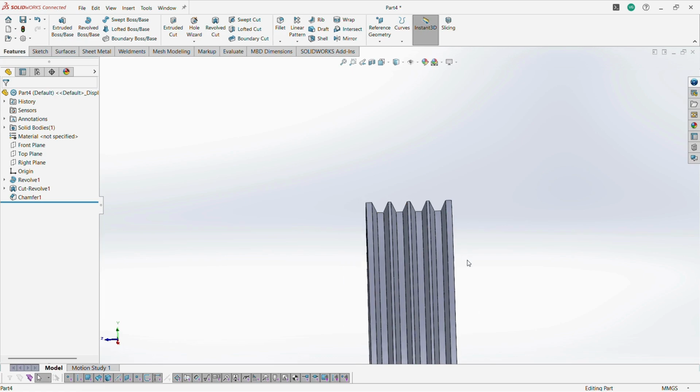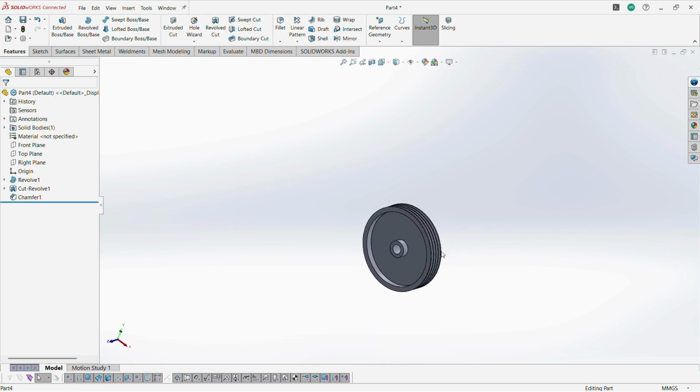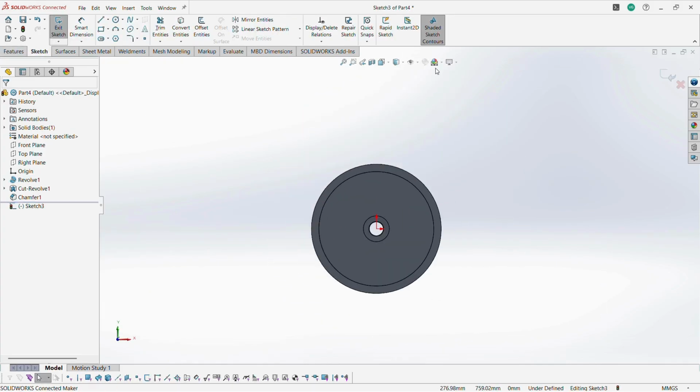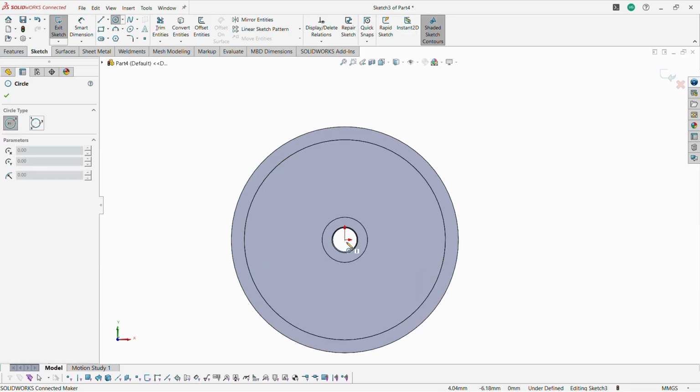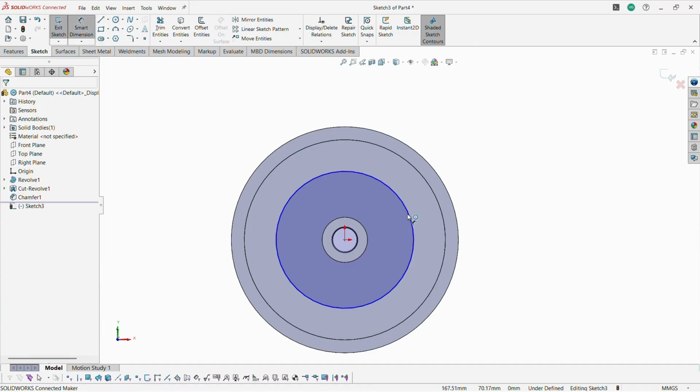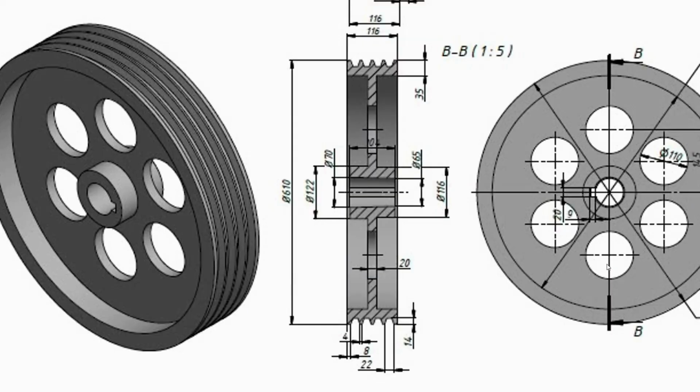Look at it. Now we have automatically created the teeth formations. Simply, let's draw the rest of the portions to create a pocket. So selecting the center point, draw a circle that is a pitch circle profile. What are the dimensions for this? Take a look at our drawing.